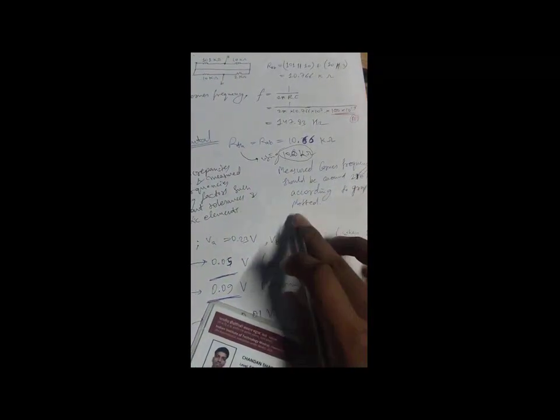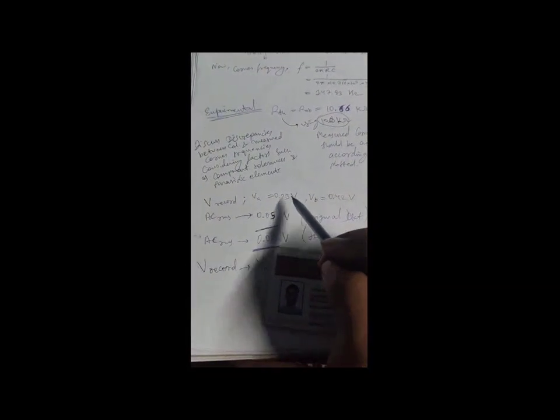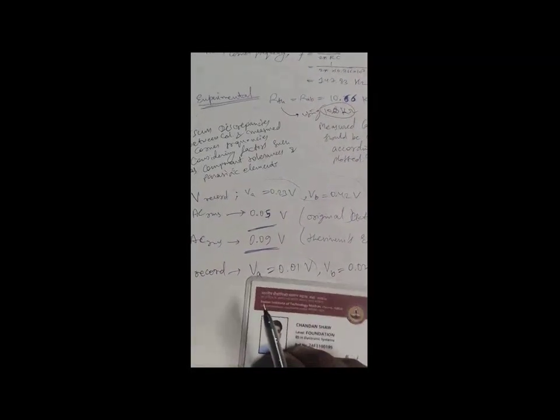The measured frequency is around 160 to 210, and the calculated frequency, 1 over 2 pi RC, is 147.83. We recorded that when DC supply is given, node A voltage is 0.23 and node B voltage is 0.42, and when AC plus DC supply is given, then VA is 0.01 and VB at node B is 0.02. The AC RMS of the original circuit is here and the Thevenin equivalent circuit is here.